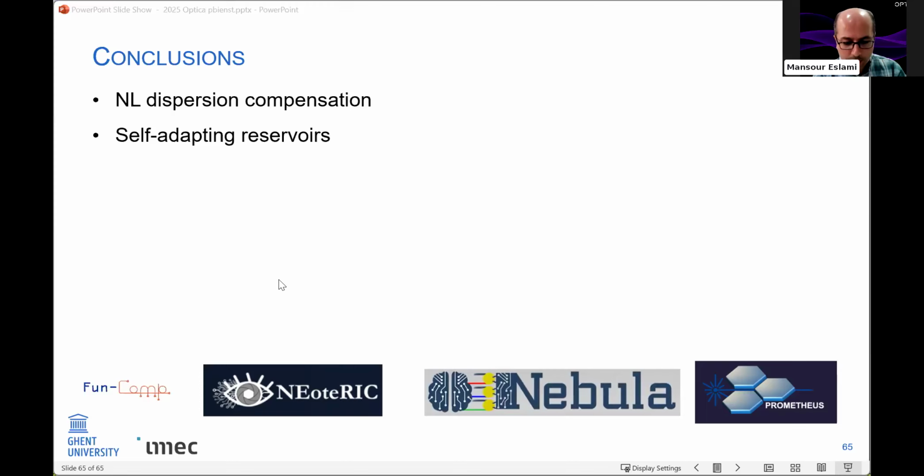Thank you very much. And is there any cooling device? Are there any heating problems, so that you need to cool down the system? Yeah. So for these telecommunication tasks, we do have some thermal stabilization. We do have a Peltier cooler under the chip. It's not an extremely accurate one, so we have some flexibility there.